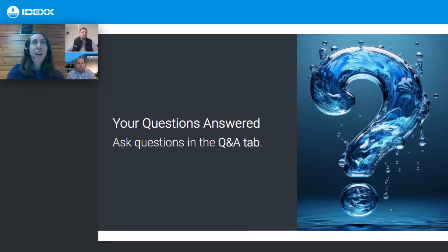But I guess that high head loss condition is a risky one from a filtration perspective, because the smaller spaces you have between your particles, the higher velocity your water is, and the more likely you are to shear off anything that you've attached to your media. So, as I said, that's one of the elements of good practice, because turbidity isn't necessarily a good measure of whether it's working or not. But you know that if you're consistently backwashing on high head loss, that you're probably at a higher risk scenario. I hope that answers the question.